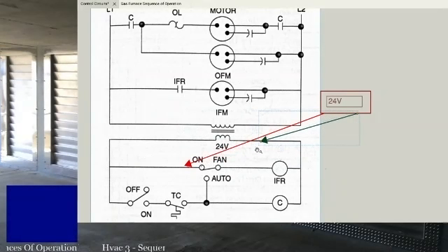The other option is if you're right there at the equipment somewhere, you can check and make sure you got your signal coming back from somewhere else. And we'll talk about checking those too. But what I really want to talk about is as you're troubleshooting individual components, all right, you want to keep your common lead somewhere on the common side. So this is the common side of the transformer, and then this other side is your 24 volts.